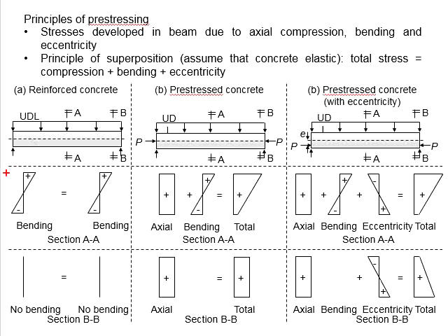Assuming that the stress is linearly distributed throughout the cross section, that will give a straight line for this stress diagram. Therefore, the stress at section AA due to bending will look something like this. As there are no other external loads, the stress within the beam member for the reinforced concrete will be purely due to bending.